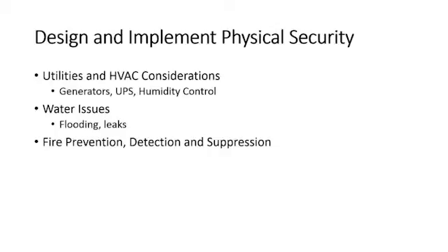If it's not an option for you to be down at all, you could have inline UPSs and generators on the back end. Because sometimes, let's say the power goes out. Well, what's supposed to happen is that the security system is supposed to kick the generator on and say, okay, hey, it's time to come on. We've lost power. But it takes a second, right? There's a motor in there. It's got to start up. It's got to start the generating process, and then electricity will start coming through. So you may be down for 15, 20, 30 seconds until that can kick on. That's why you want an inline UPS, that battery power, to give you that time for the generator to start up. So put those in line. And you may have diesel power generators, natural gas generators, whatever kind of generator you have. But once the generator starts, then it could power the building or power your data center so you're not down.